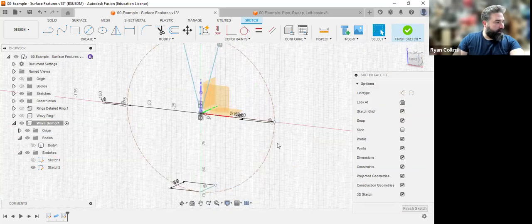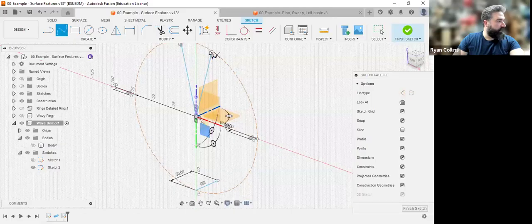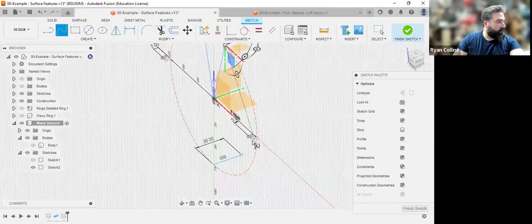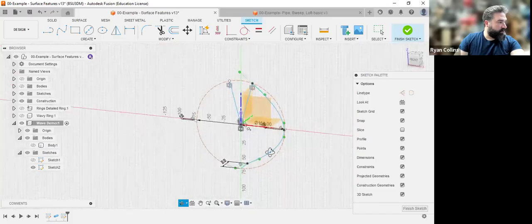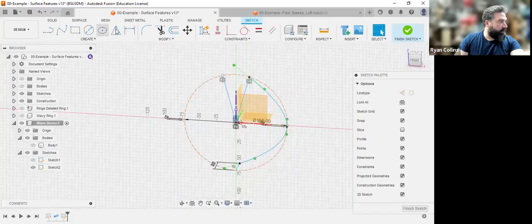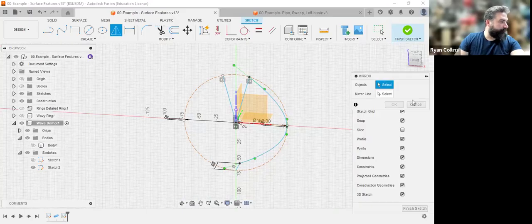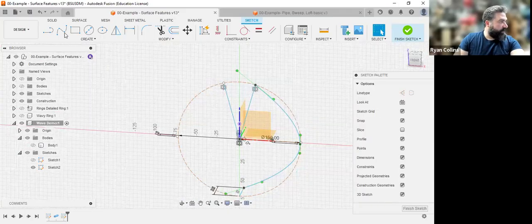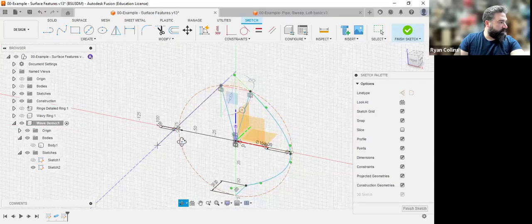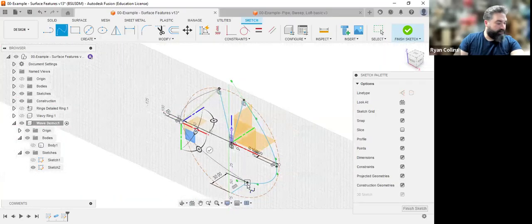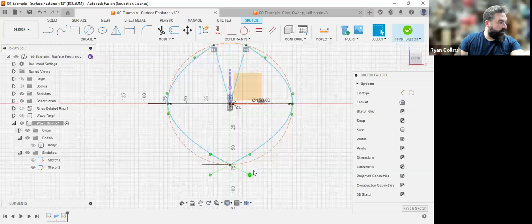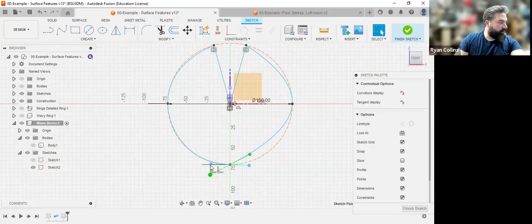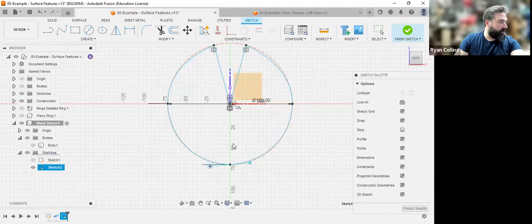All right, cool. So now I could go around and use my fit point spline to make my copies. Still super weird that it won't let me mirror that line. Anyway, do the same on the other side, meaning connect to point, connect to point, connect to point. Now I just got to go through and make your adjustments for your fit point spline handlebars. Let's get those to match, or at least as closely as we can.